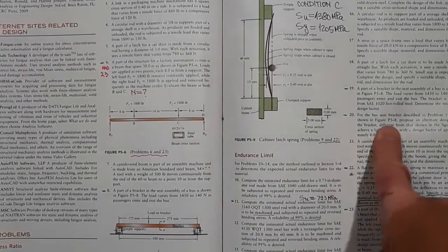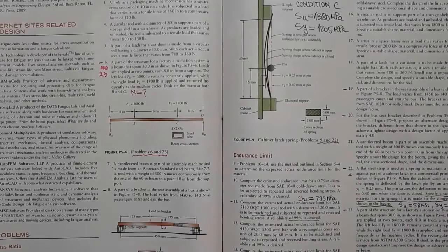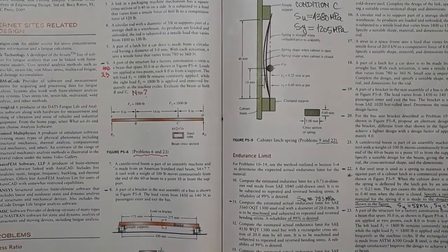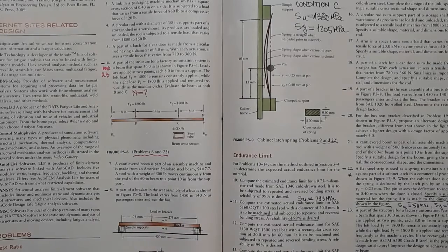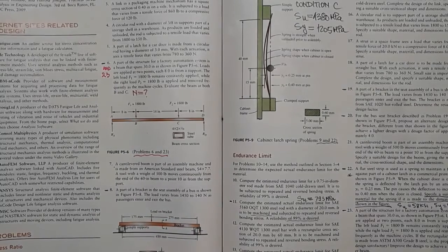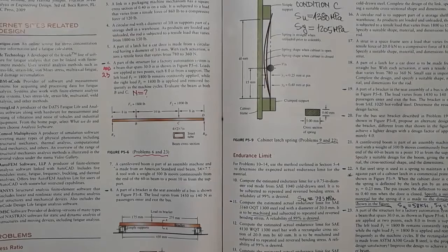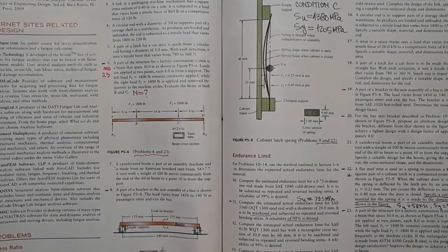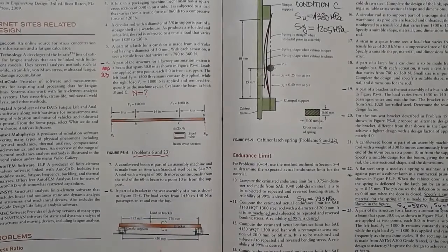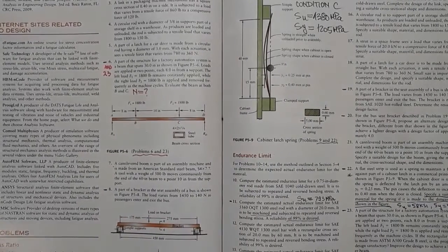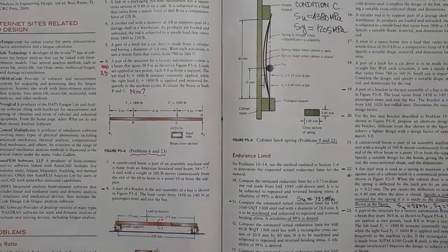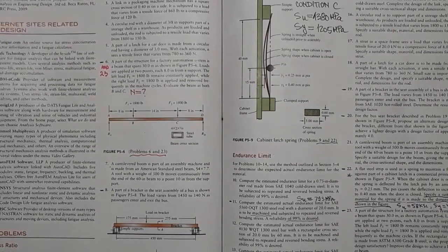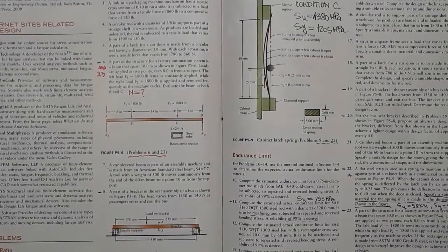I'm not going to emphasize this. It would be a matter of increasing the area moment of inertia, make it more bend resistant. Really, if you flip the flat to have it 60 millimeter height and 12 millimeter wide, so if you rotate 90 degrees, it will be much stronger in bending. Okay, so let's look at problem 8.